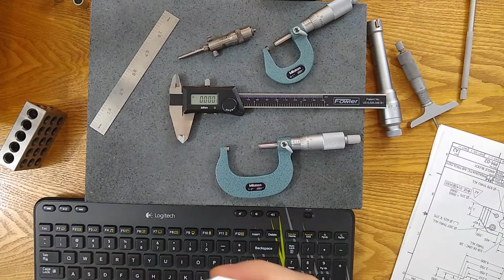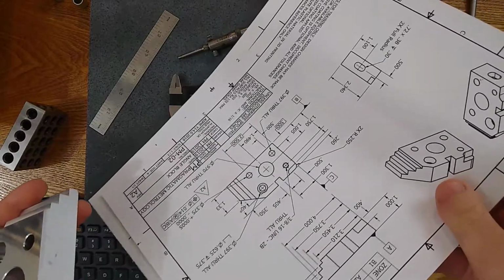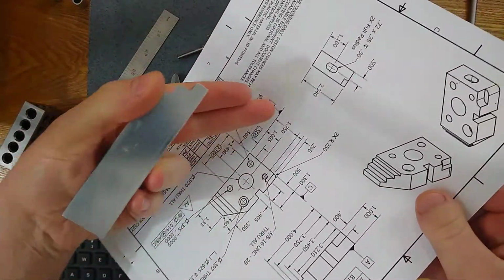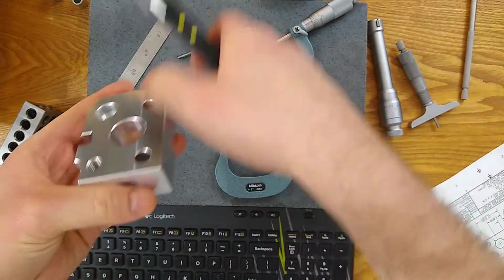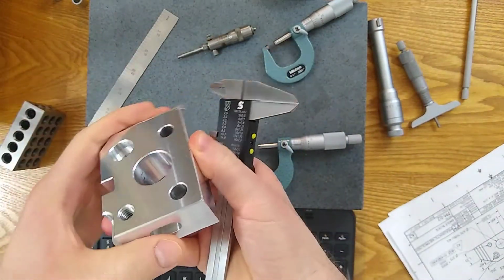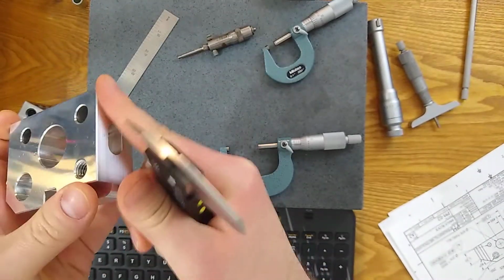Question 4, briefly went over this already. Are any part reference surfaces necessarily in good condition for the measurement? Will the error of the reference surface greatly affect the measurement? Oftentimes it's not uncommon. Prints will reference from one feature to another, and in the example of holes here, the location of these holes is called off the bottom surface and the side surface.